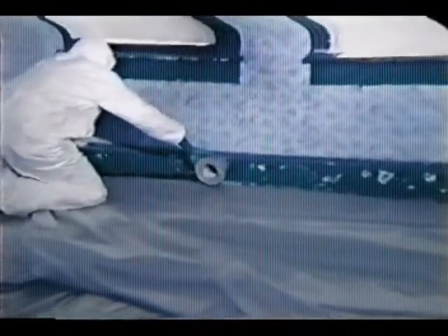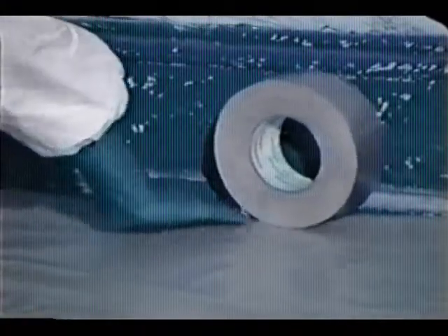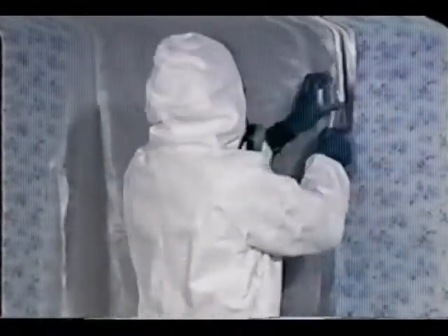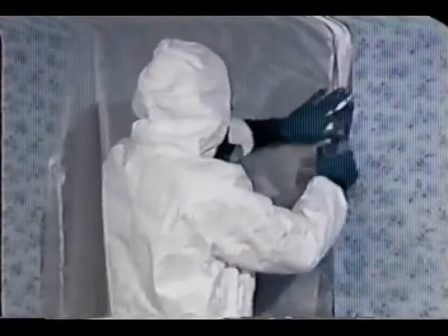Therefore, they should be covered with at least 2 layers of plastic sheeting 6 mils thick. By layering the plastic, the top layer may be damaged and repaired without exposing the floor to dust and debris. The base layer should not be removed until just before the final cleanup. The edges of all layers should be sealed at the walls with tape. The areas not involved in abatement should be isolated from those that are by sealing the connecting doorways with plastic sheeting and securing it at the edges.